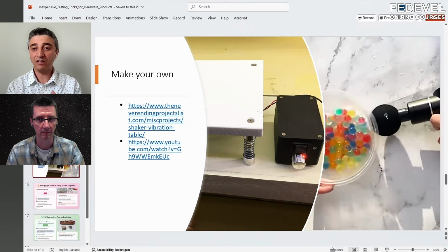If you have a mini container, you can put your product in. You can basically hit your design so that you cause these vibrations. They are not exactly the same vibrations that might be in the field, but this will expose any weakness in your design. Like you mentioned, it could be a heatsink, it could be a solder joint. Easily, if you vibrate it with this gun, it might be detected and you can find the issue right away.